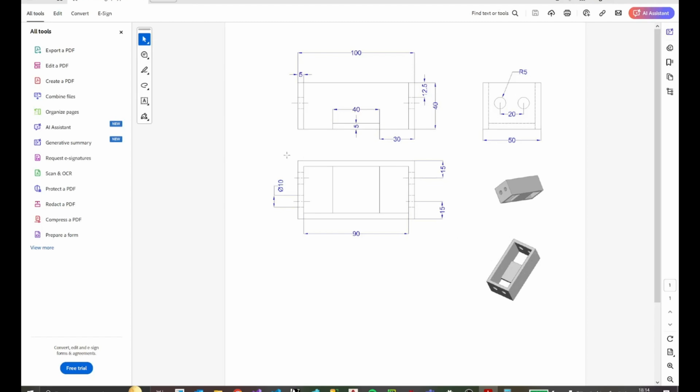Okay, so what I'm going to do is I'm going to make this profile of this rectangular box thing, which is this one, and I'm gonna go from there. So from here you can see it's 100 units from here. Since the drawing doesn't show any units, I'm just gonna assume it's millimeters, right? So this is 100 millimeters from here, and over here it's 15 plus 15, which is 30, and this gap is 20 between the centers of these two holes.